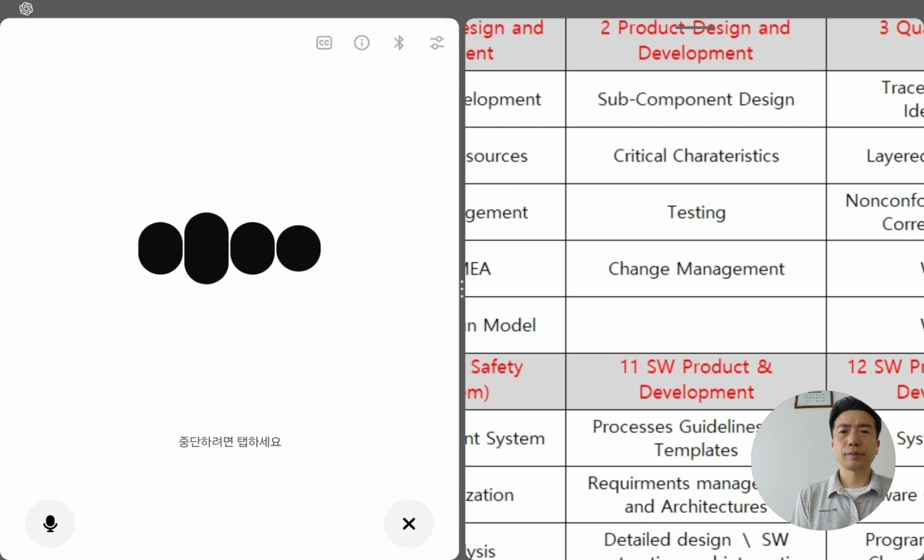Two, what flagged means in FMEA and control plan. In this context, flagged means highlighted, marked, or indicated. It doesn't mean a real flag. It means text or a symbol to show importance. Example: in the PFMEA, critical characteristics are flagged with CC or SC notation because they are marked, identified in the table.